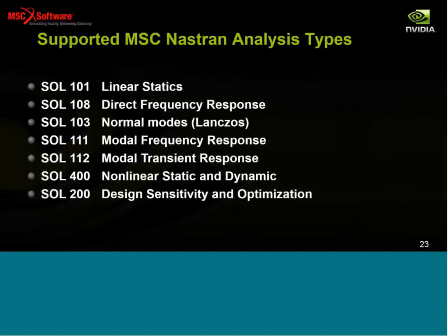So I mentioned before that the GPU is supported in several solution sequences. It can be used in all of the following. One thing to note is that for solution 103, it is only useful for the Lanczos method at the current moment. We do have plans in the future to address ACMS, since we have a big redesign of the ACMS algorithm that's expected to be released in the future, but for now it's only supporting Lanczos. So in the next several slides, what we're going to look at is when the GPU performs well, how well does it perform, and when is it recommended to be used. So now we're going to look at some actual performance results.